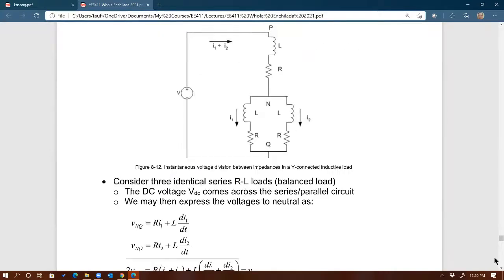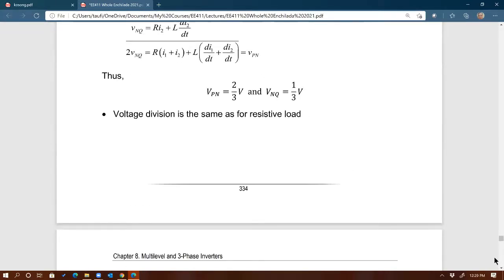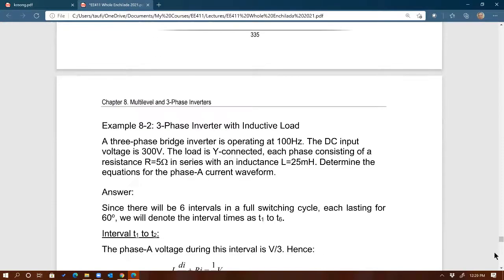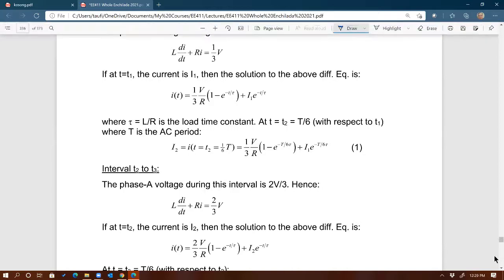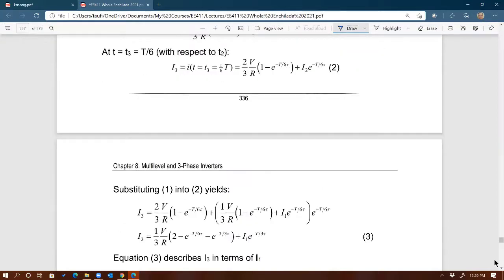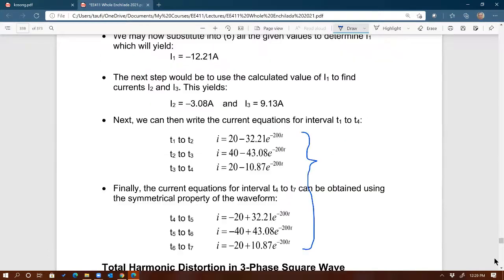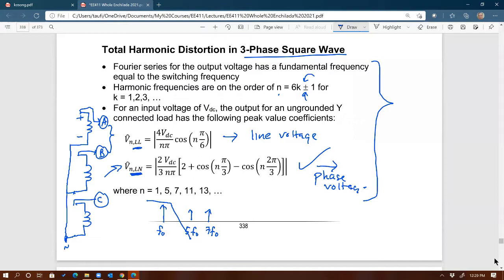So why are the multiples of 3 left out then? What's causing that? What's sort of picking those out? Oh, it's just the symmetrical property of the waveform. You have to go back to the Fourier series. There are certain properties of the waveform where some triplet harmonics disappear.